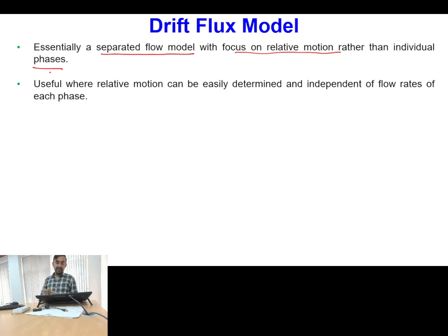But in the drift flux model, once again we are interested in combined phase equations only. So my interest is in combined phase continuity, combined phase momentum and combined phase energy equations. The only one additional equation I will consider is for the relative motion between the phases, and with the help of that equation, we will be able to develop some of the basic criteria. So a very detailed analysis we will not get from this, but some preliminary idea we will get.